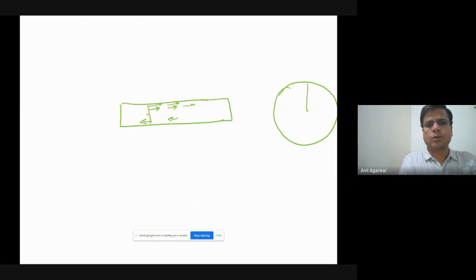So at the centroid, it's small. As we move away from the centroid, it is larger. Similarly here, it is larger, and this is the shear stress that is being applied by the subsequent cross section. So one cross section is applying this kind of a shear stress on this cross section. Similar thing happens in a circular section. So you have this kind of shear stresses.